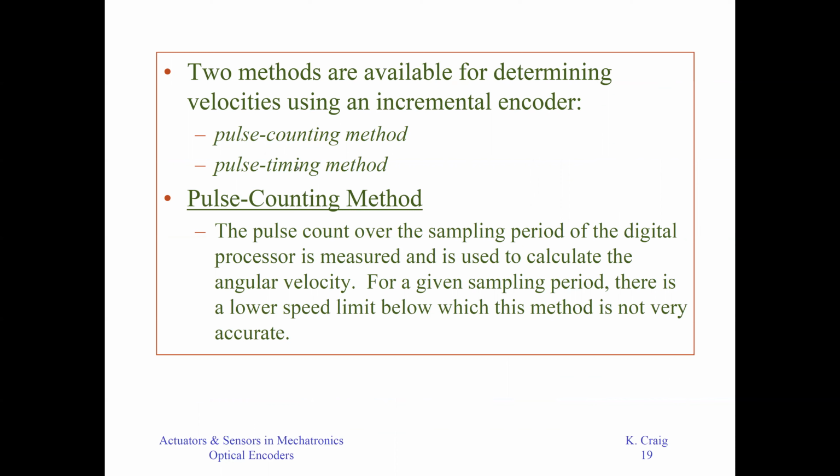In a microprocessor, you have timers and counters. But good news is that there's already a dedicated encoder chip. You just put the encoder signal in here, and they will give you numbers. Within this chip, you need counters and timers, which a microprocessor has already.